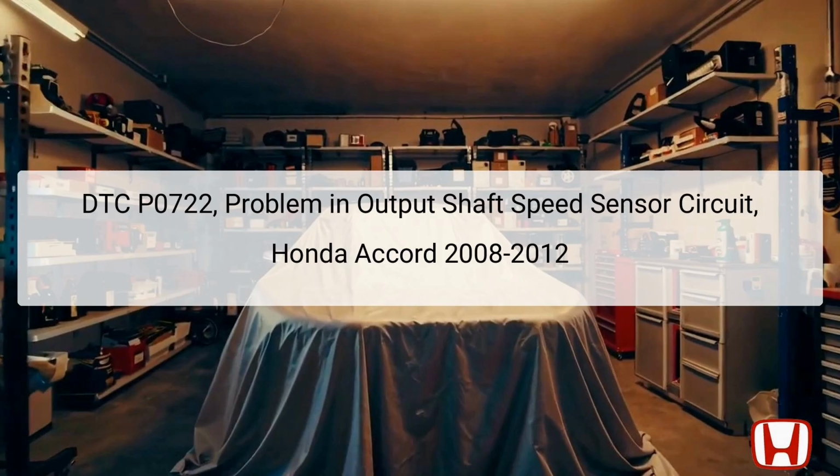The output shaft speed sensor is located on the transmission housing and is responsible for measuring the rotational speed of the output shaft, which plays a vital role in the vehicle's shift control strategy. A malfunction in this sensor can lead to improper shifting, reduced fuel efficiency, and overall impaired vehicle performance.